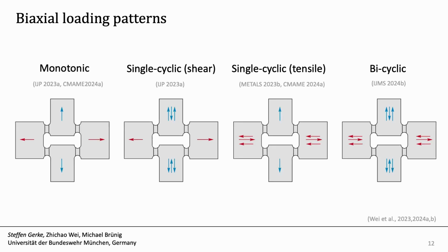How to call these experiments? First, we started out with monotonic loading, meaning we are loading both axes simultaneously and monotonically, causing a stress state here in these notches and plastic and damage behavior occurring there.